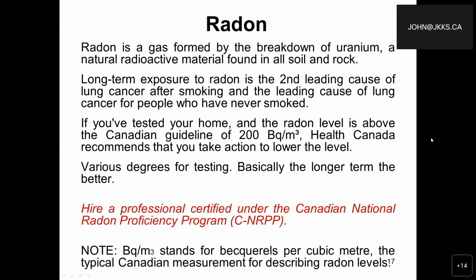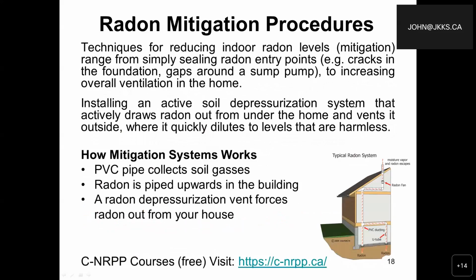Thanks, John. Good to know. And as we mentioned, we will be having another webinar in more detail on the radon issue. Just to follow up a little bit on the radon mitigation John was talking about, there are techniques for reducing indoor radon levels, what's known as mitigation. They range from simply sealing the radon entry points, cracks in the foundation, gaps around the sump pump, etc., to increasing the overall ventilation in a house.